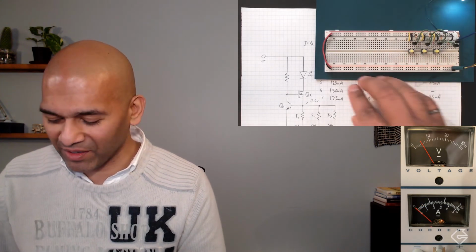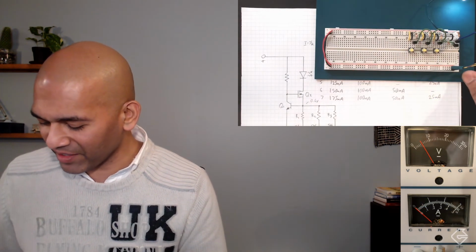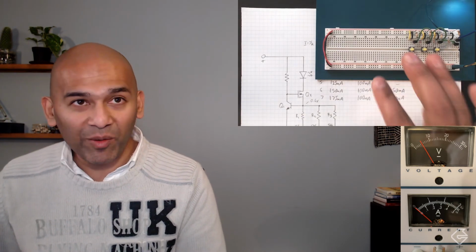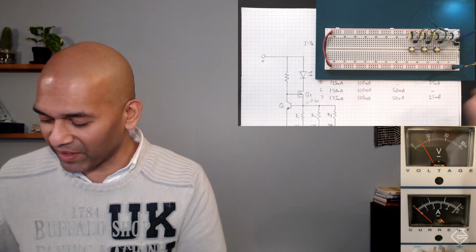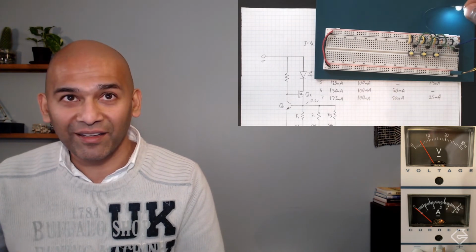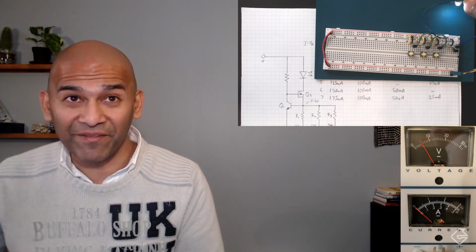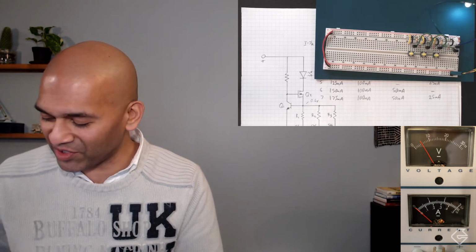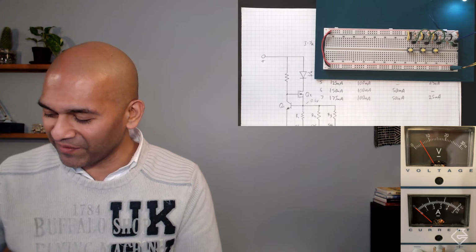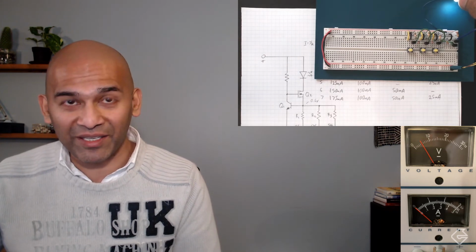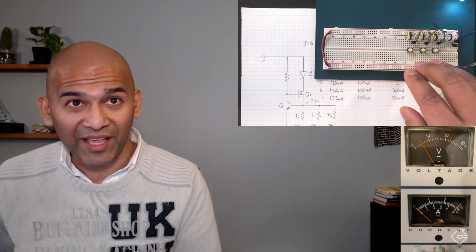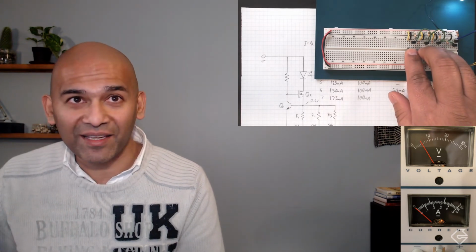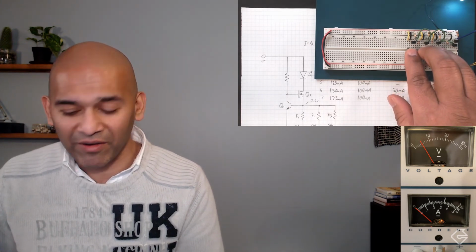So what's going on here? There's something very interesting going on here. There's also something else interesting going on as well. If I don't push any of the switches, I got no current flow. But look at my LED. It's actually glowing very dim. So what else is happening? Because there's something else fishy going on here as well. So we're going to have to figure out why my LED is glowing dim even though I haven't pushed any of the buttons, and also why I can't seem to get the right current out of here.